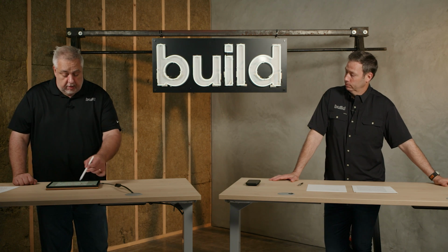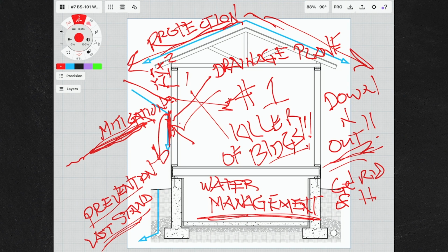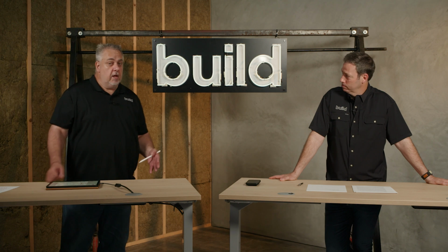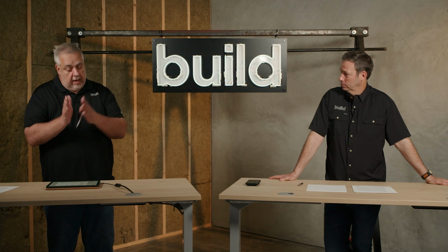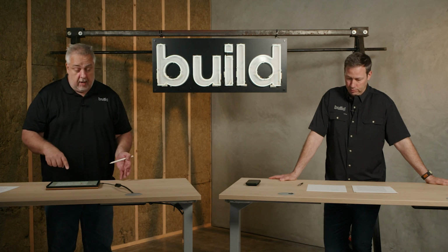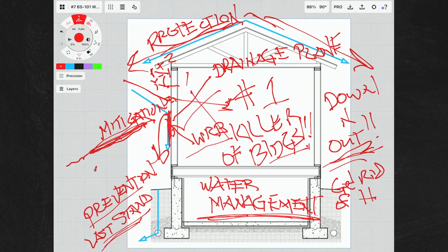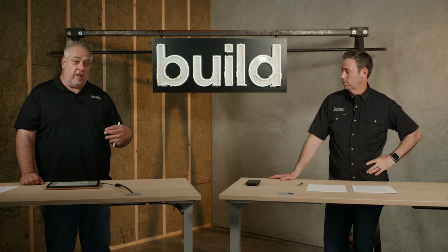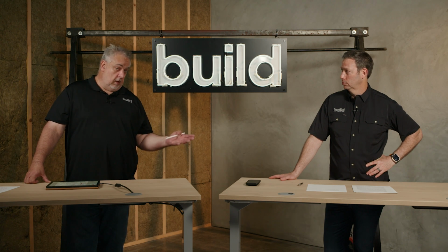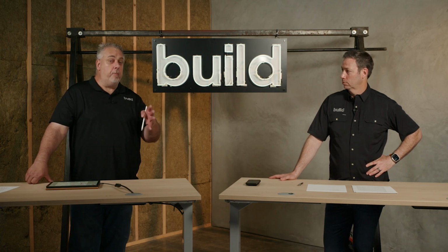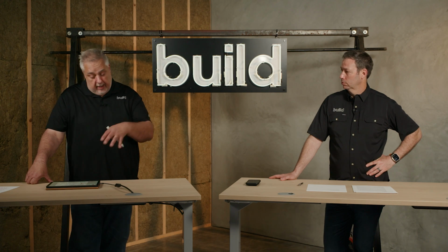Right. And that drainage plane is very commonly referred to as the WRB. That's right. Or weather resistive barrier. There you go. So that is our last stand, weather resistive, like it's stopping everything at that point. And it's the first time in this whole series where we've used the word barrier. That's right. So the difference between management and barrier is a stopping point. Yep, that's the Alamo. That's where it all ends, right there. So we're either successful or, like the Alamo, maybe not so successful. But our hope and strive is to be successful at that layer.